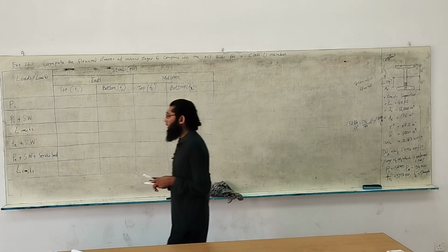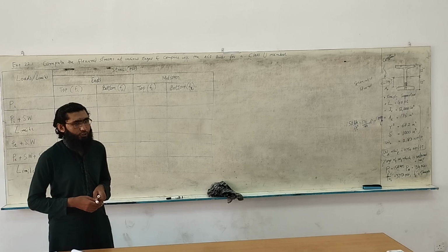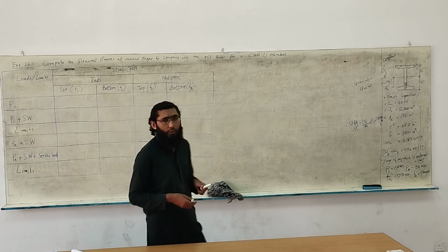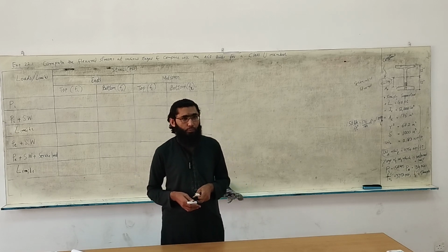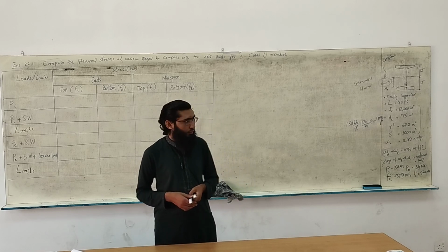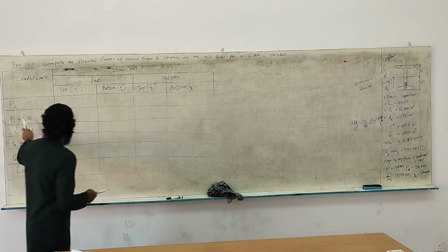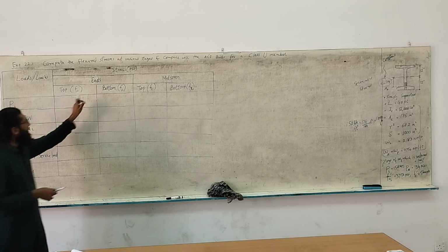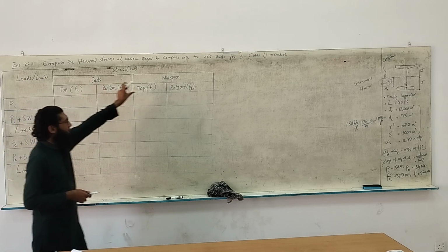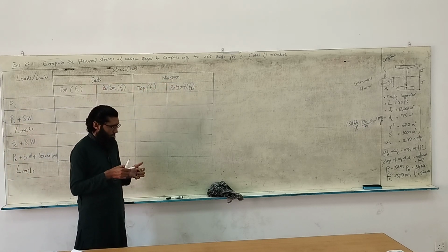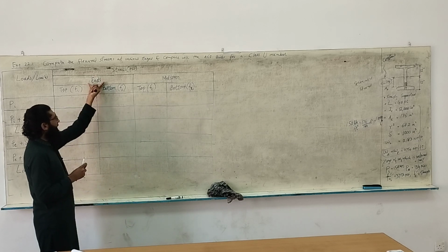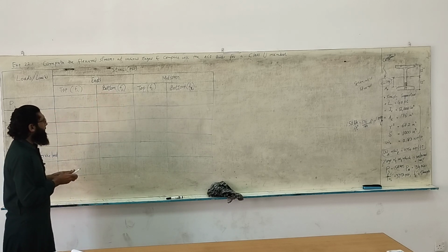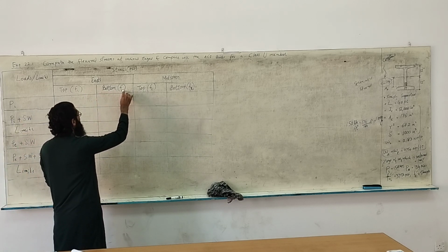What we are going to do is calculate the flexural stresses at various stages as the loads are applied, and compare them with the corresponding limits for a class U, uncracked member. Okay, so let's get started with the first phase. I've listed the loads and limits in this column, and I'll calculate the stresses at the ends and mid span. At the ends and mid span, I'll be calculating the top and bottom stresses.